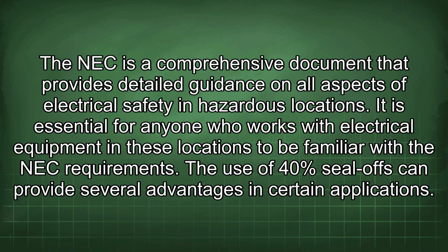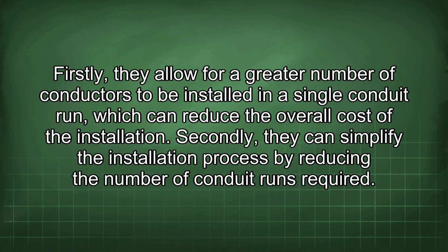It is essential for anyone who works with electrical equipment in these locations to be familiar with NEC requirements. The use of 40% seal-offs can provide several advantages in certain applications. Firstly, they allow for a greater number of conductors to be installed in a single conduit run, which can reduce the overall cost of the installation.